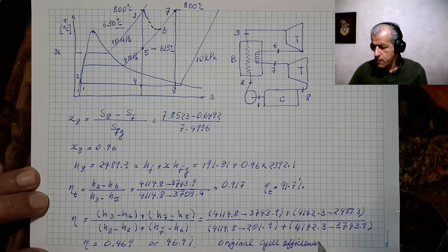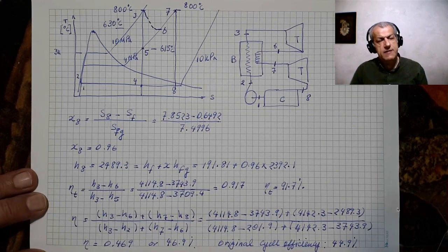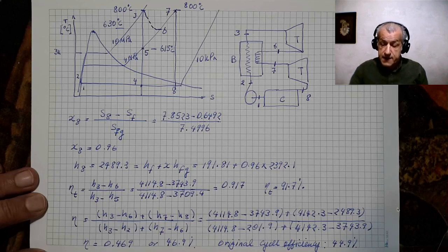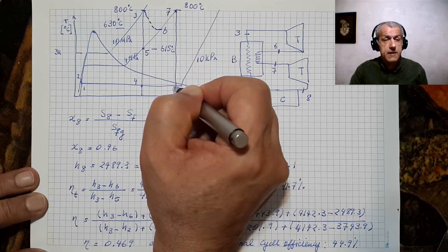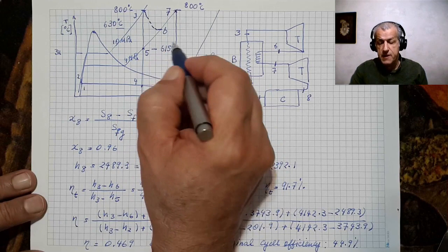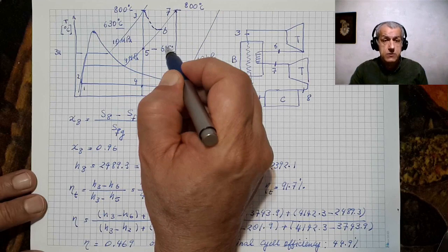efficiency was 44.9%. So adding this reheat has in fact increased our total efficiency. If you remember, in the gas turbines, this didn't happen. Adding reheat reduced efficiency, since in the gas turbine, the reheat part didn't expand to lower temperatures. So it was just a cycle up here, and it had a lower efficiency, and therefore it reduced efficiency